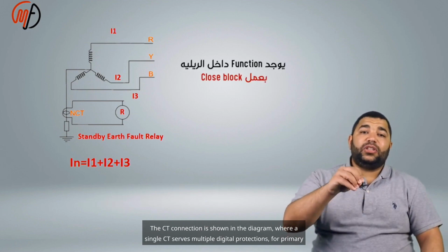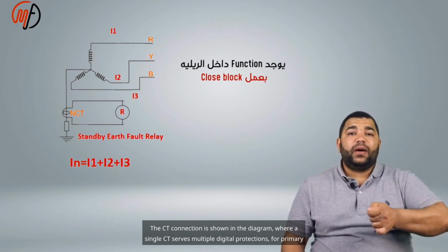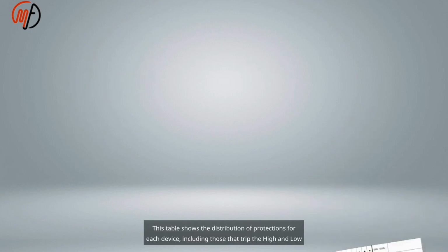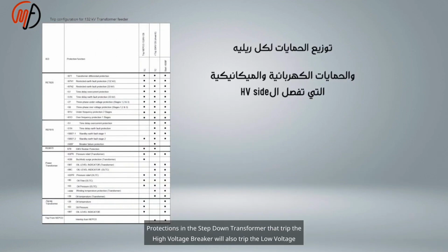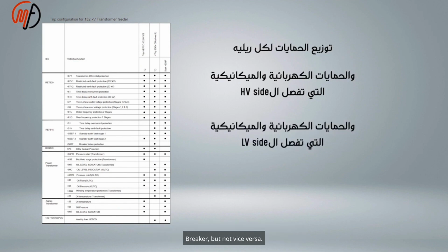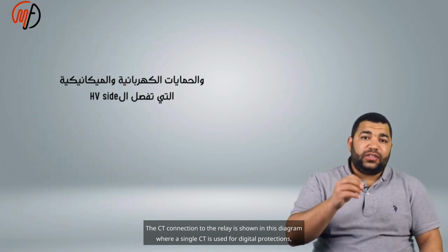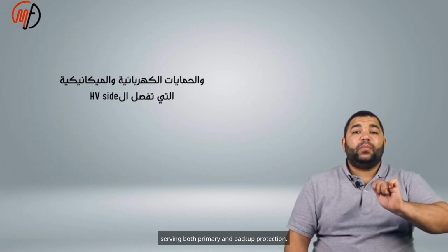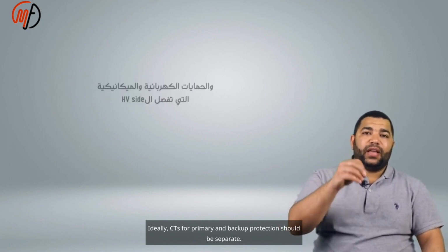The CT connection is shown in the diagram, where a single CT serves multiple digital protections for primary and backup. This table shows the distribution of protections for each device, including those that trip the high and low voltage sides. Protections in the step-down transformer that trip the high voltage breaker will also trip the low voltage breaker, but not vice versa. Ideally, CTs for primary and backup protection should be separate.